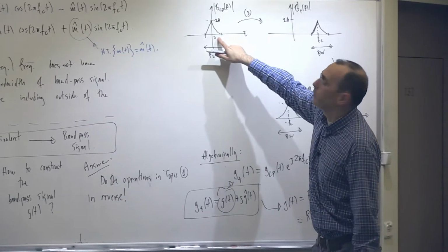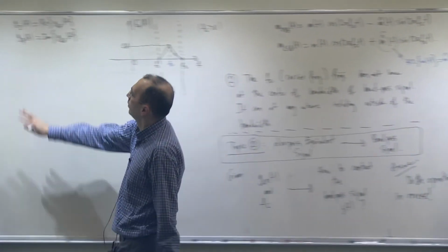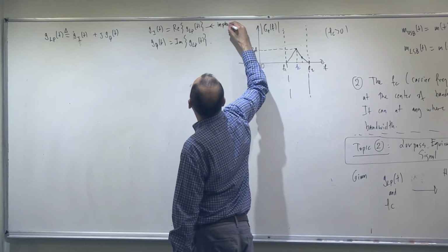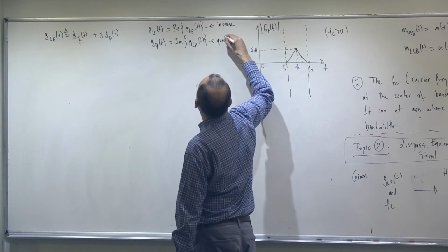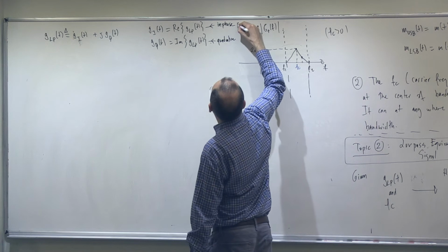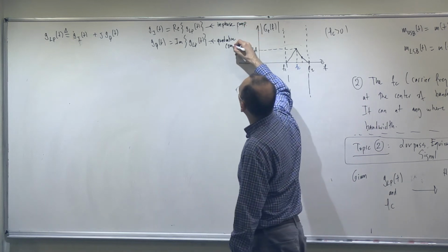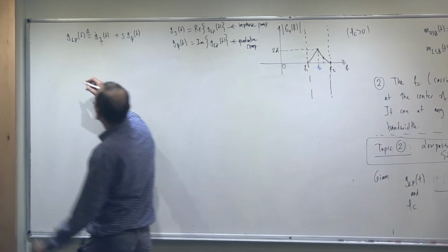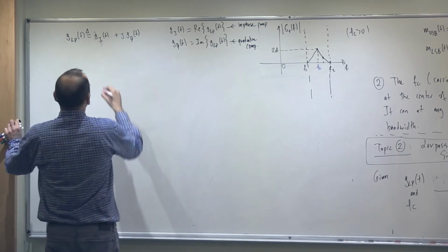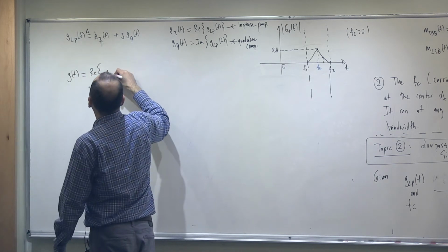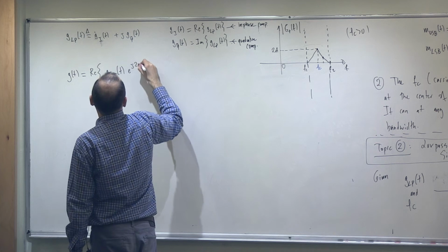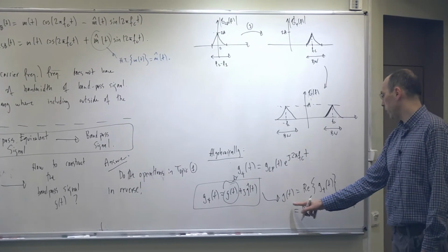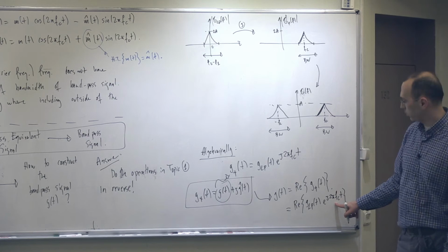Now I'm talking about this in time domain. Complex valued in time domain. The real part is Gi, and I will call this the in-phase component, and Gq I will call the quadrature phase component. Okay. Then G of t, one more time, writing this: the low pass equivalent modulated to the carrier frequency and taking the real part. G of t is the low pass equivalent modulated to the carrier frequency, taking the real part.